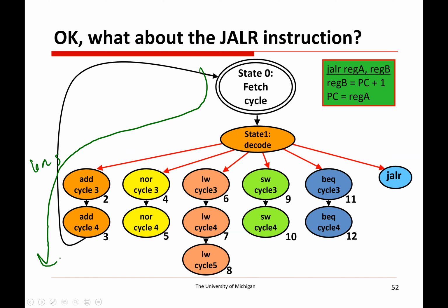Let's just start the next instruction early. No, we can't update the memory until the next clock tick. So we just end up sitting around for several nanoseconds, even though we finished early. We're not benefiting from the fact that this was a shorter instruction. And because the load word instruction, I think we said, takes 9 nanoseconds, that was the worst case scenario. So we had to set the clock period to 9 nanoseconds.